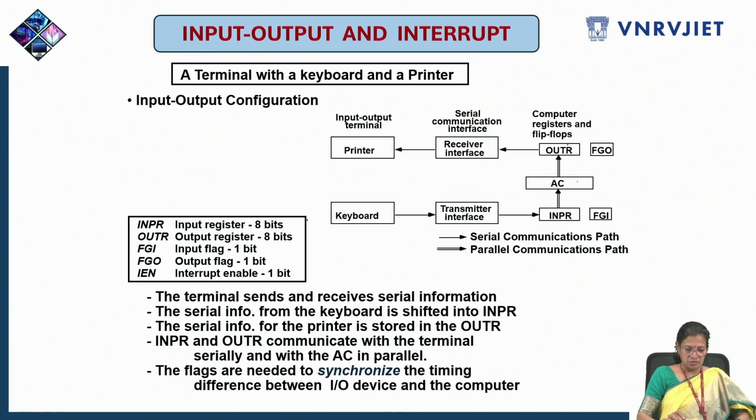Okay. So as we have already seen, these input output registers are 8-bit registers, and we have the output flag and input flag, which are single-bit flip-flops. These will indicate whether it is available, whether it is ready for inputting, ready for output, or enable input, enable output for that purpose.